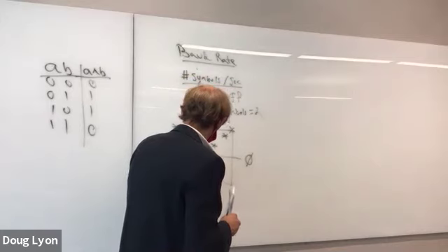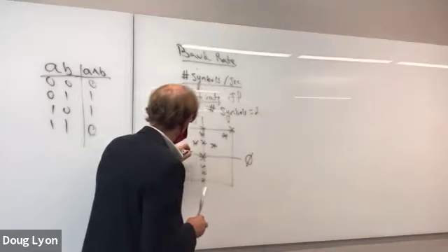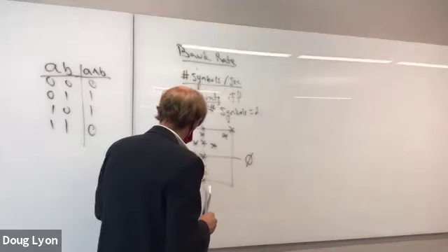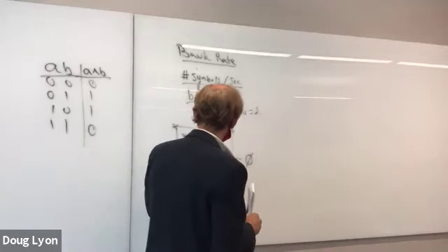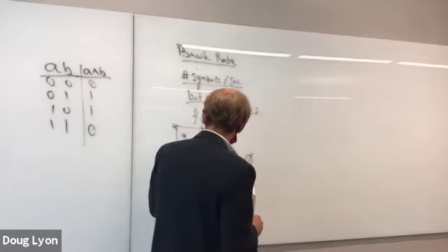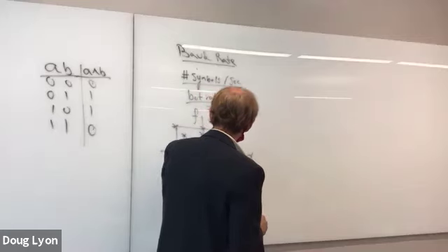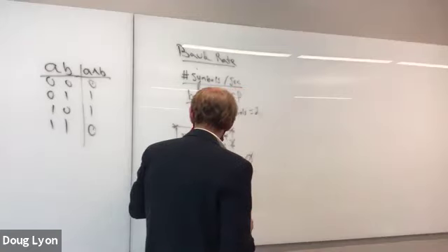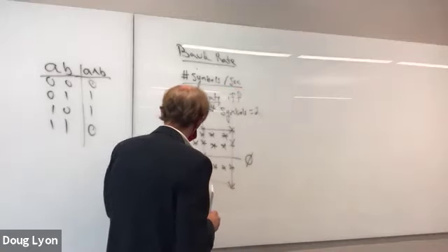And your maximum a posteriori receiver, also known as the MAP receiver, has a series of filters, which is able to determine when these symbols are being sent. And you can imagine it's just like a touch-tone phone where you send different numbers that have a dual-tone multiple frequency system associated with it. As many of these as you like, as many as can be efficiently discriminated against.